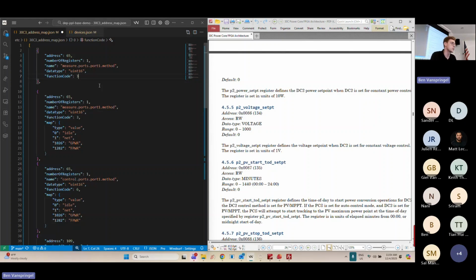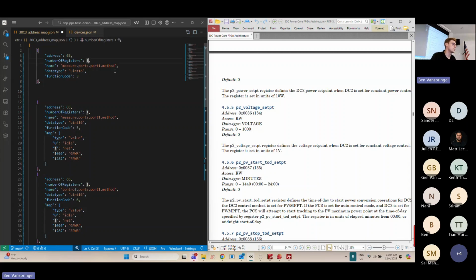You'll get timeout issues. So what Modbus also does is, well, we call it a multi-read. So you can read multiple registers at once. So the maximum Modbus can read together is 125 registers. So that's what I'm going to do here as well. So I'll start from address 65. And what I'll say to this first register, I want you to read all these registers all at once.